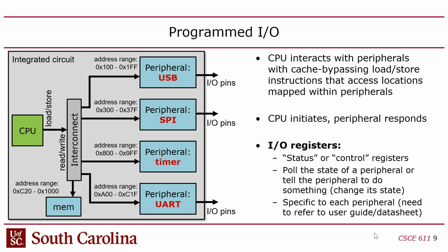They're not serial buses. Serial buses are usually used for off-chip access. You guys with me? Like you wouldn't use a serial interface for on-chip communication because they're too slow. Right? Parallel buses are faster because you're sending multiple bits in each cycle, right? But I haven't talked too much about parallel buses, but the point of this is that each peripheral has a special range, and then we can read or write to that range in order to perform communication between the CPU and the peripheral. Make sense? So this is still kind of a master-slave style interface.